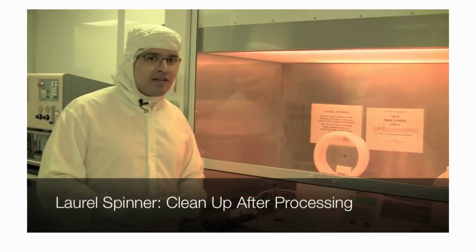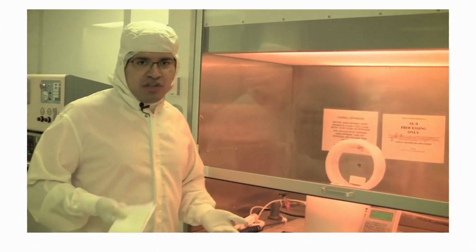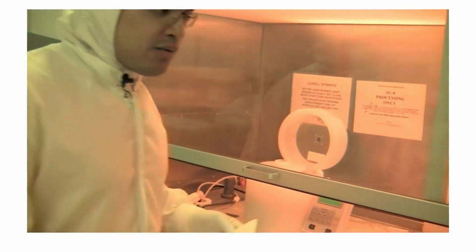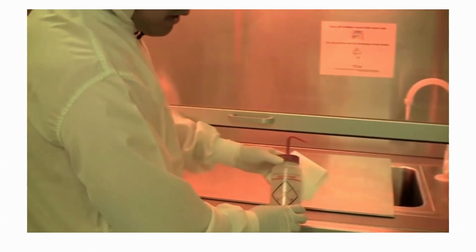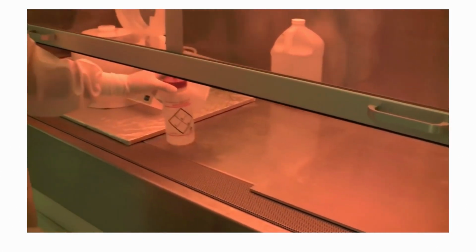So once your sample is baking, this is a good opportunity to start cleaning the spinner. Now, you only want to clean when you're done spinning everything. So I recommend if you're doing 3 or 4 wafers to spin them all first, so that all you have to do is clean once. To clean the spinner, you want to use acetone. It's usually located on this side of the hood, and it's denoted by this red bottle that says acetone. If this bottle is running low, we usually have spare bottles over here.